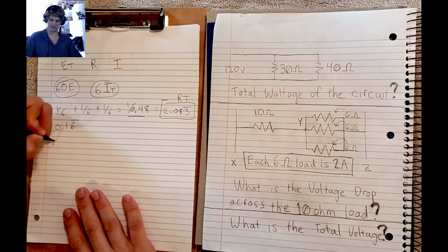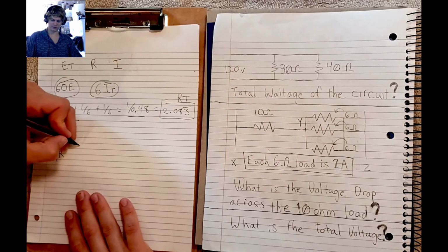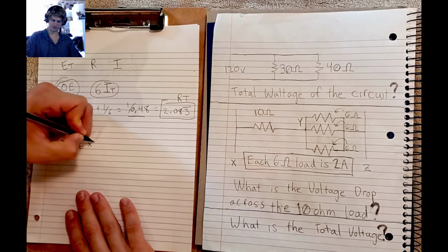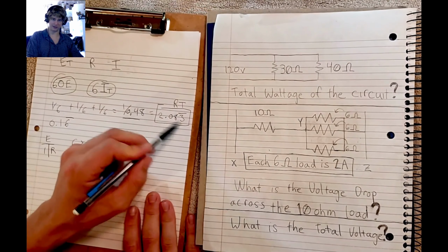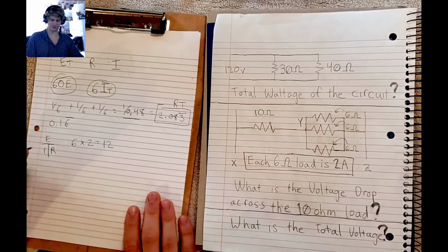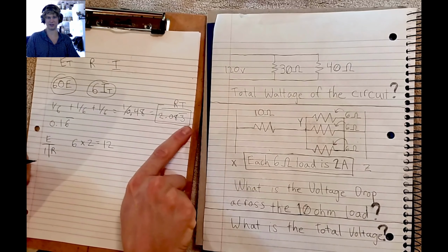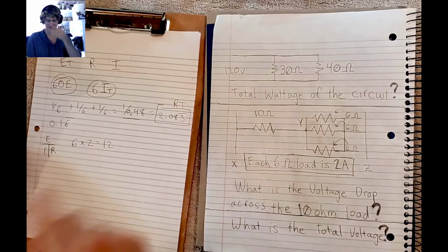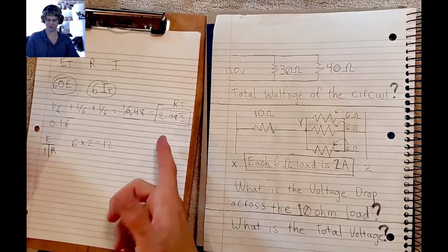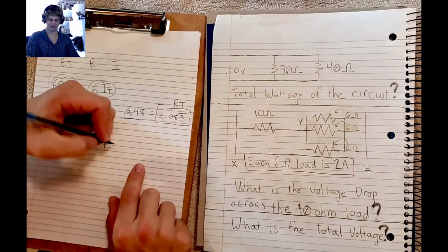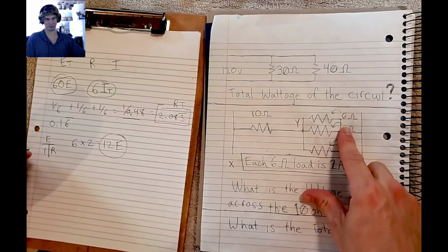And now remember, we're using the E equals I times R, what I call ear. So I times R, we'll do 6 times 2, we'll get the number 12. And of course we could have added those numbers, but it's such a small number that I'm thinking that of course we're going to be rounding down with the 0.083. It could be 2.1 technically, but I'm assuming we're just going to use the number 2. So we have 6 times 2, we have the number 12. And of course that is that voltage for the section of resistors wired in parallel.